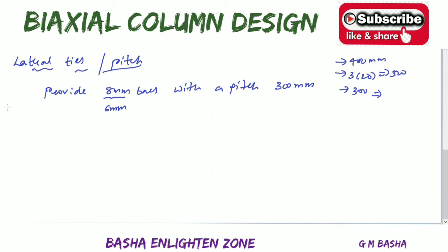So the condition is not less than 6 mm, and again the first condition is diameter by 4. Here we are using 20 mm bars, so 20 by 4 means you will get 5. So provide 5 mm also. If you use 8, 8 is also okay. Why? Because the least will be 6 mm, not less than 6. Then I am providing 8 mm bars, which is on the safe side only, no problem.